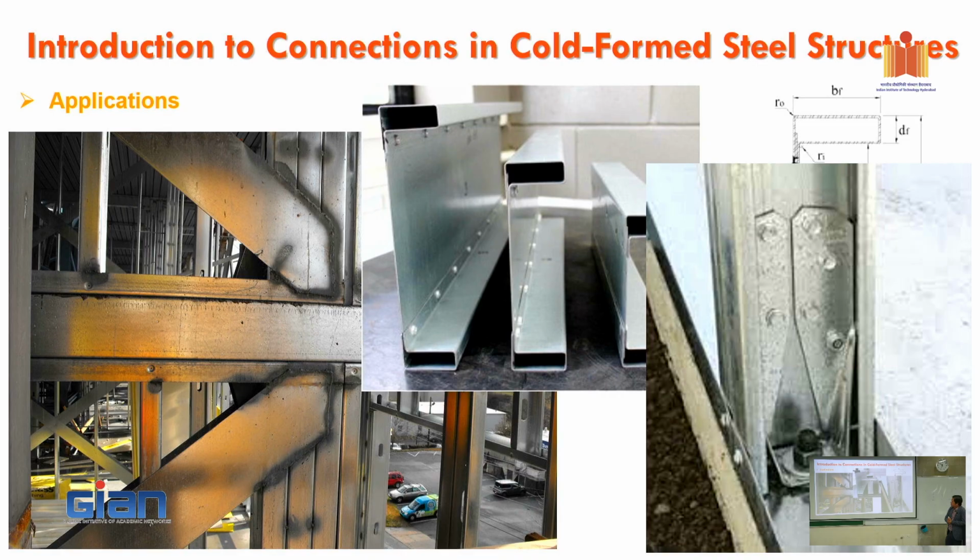In Australia, they use cold form, and then you remember the test with 2-story with the high shear load. Even their maximum one couldn't carry the shear load. Then we have to make it out of 10 millimeter thickness of hot roll steel. So I think that's designed for low rise with very low lateral load. But when we test, remember we test, I'll show you a bit later, 2-story for shear wall, and with the huge lateral load.